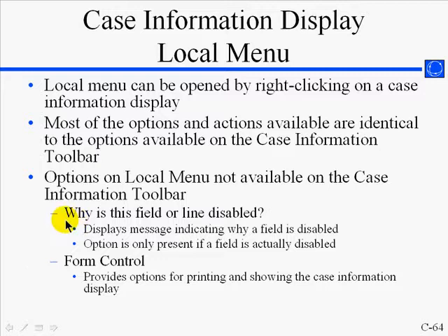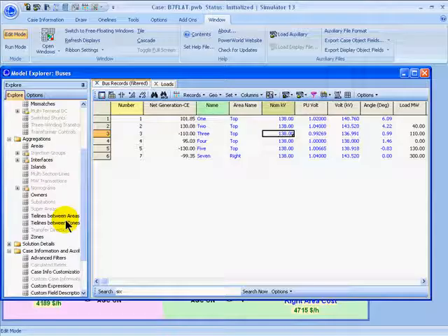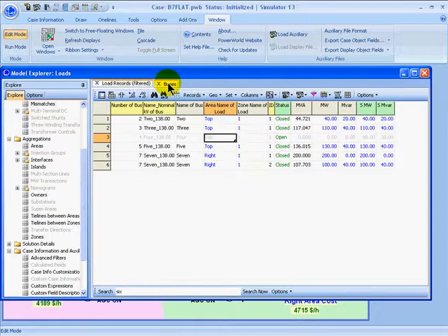So if I go into Simulator and I go back to my loads records, I can see that for this load attached to bus 4, it's actually open. The breaker status is set to open. If that's not the case in yours, you can just toggle it by double-clicking it and changing it to open. And I can see that just about everything associated with that load is grayed out. That's because the load is open, and so it doesn't really matter what the value is.